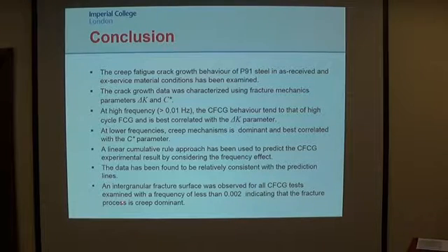And lastly, an intergranular fracture was observed for all the creep fatigue crack growth tests examined with a frequency less than 0.002 Hz, indicating that the fracture is creep dominant.